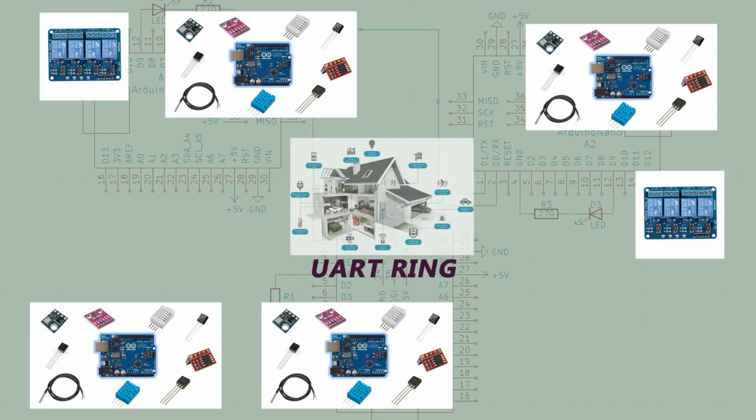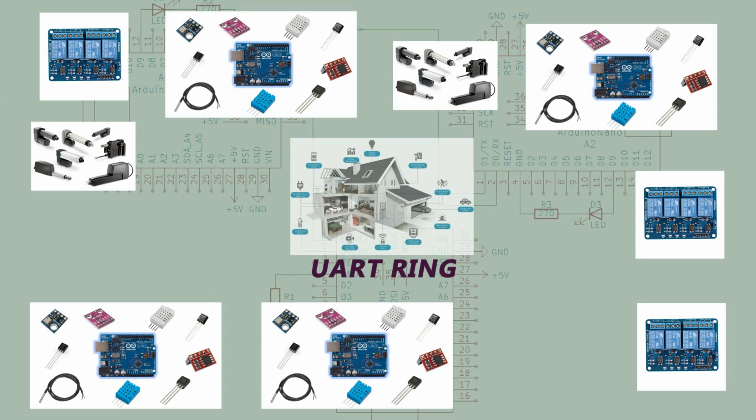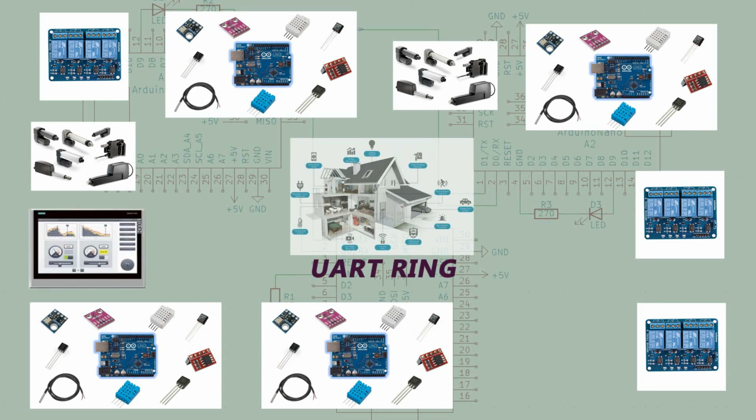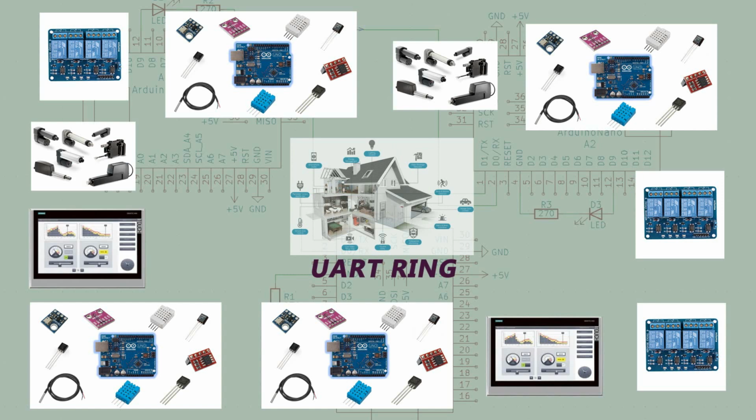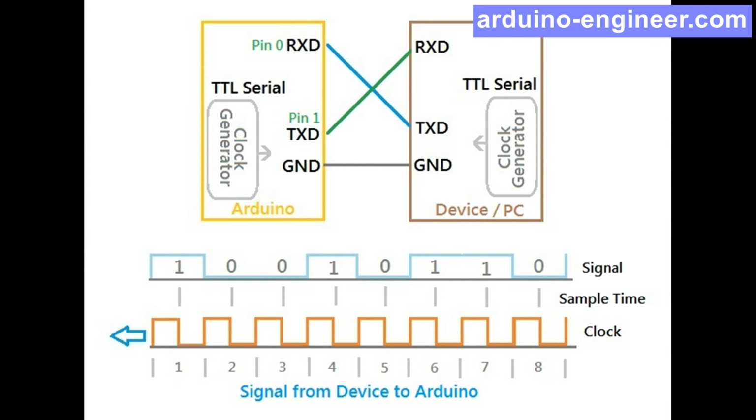I want to take as a basis the simplest, but also the most reliable of the physical ports of the controller. This is UART. I2C is also simple, but its speed cannot be reduced enough for transmission over long distances. As a rule, controllers have a choice of two high speeds. The UART port is designed to communicate only between two devices at a distance of about 50 centimeters using two signal wires. In this series of videos, I try to break the usual notions about the limitations of the UART and move towards my goal with you.